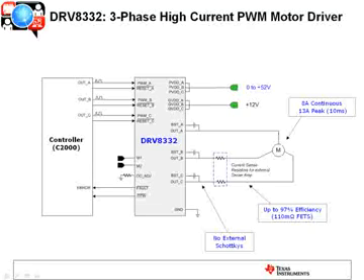And you need to be careful, make sure that you're not just reading the peak current, you need to look at the continuous current. The peak is exactly that. It's meant to, the device can withstand that level of current for very short intervals, say on the milliseconds or microseconds, just depending upon the device. That could be your peak currents during startup or stall and so forth. But continuous, 8 amps continuous, these are very efficient devices, up to 97% efficient.